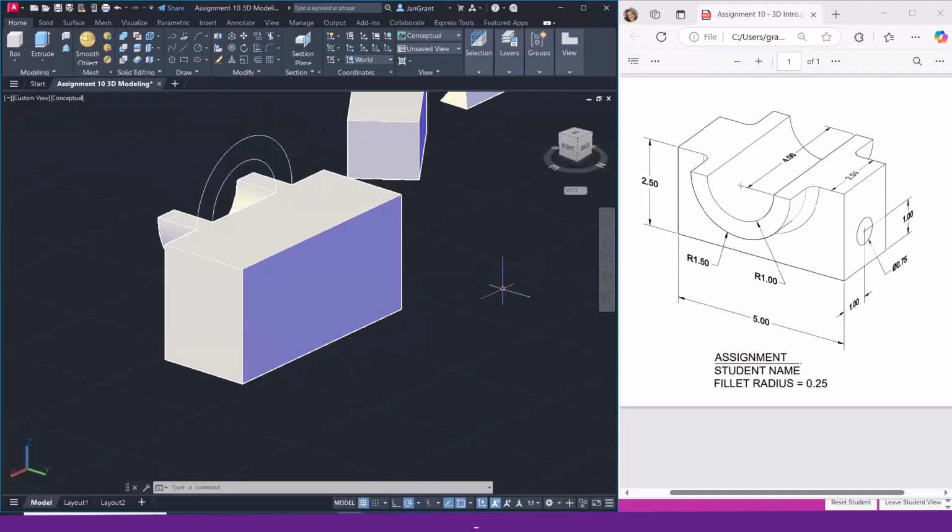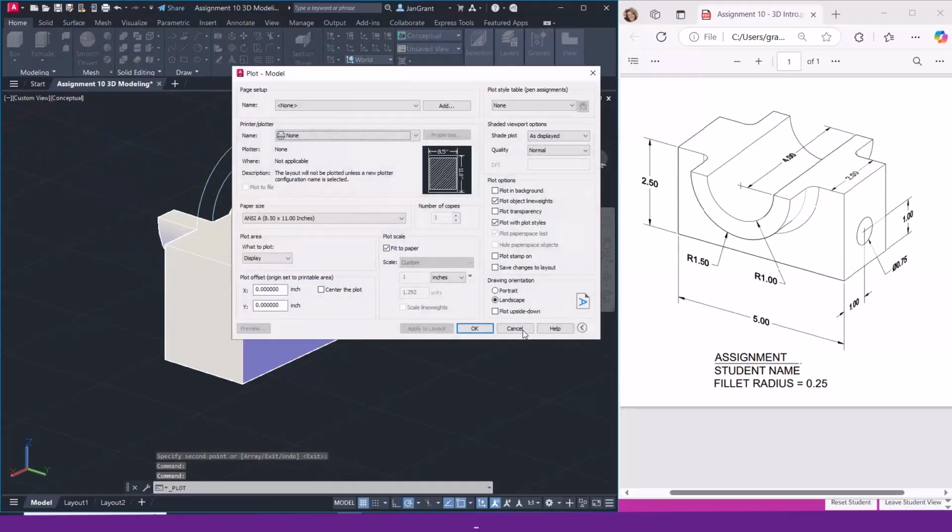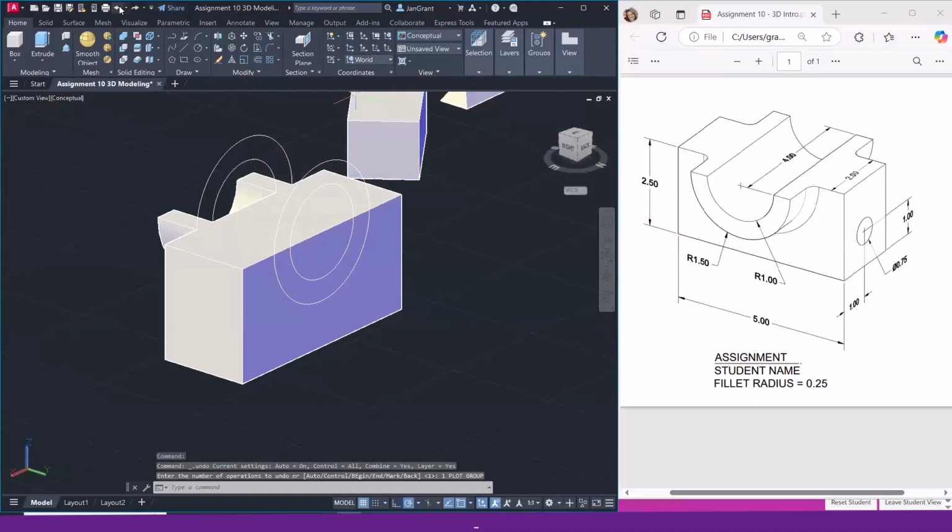I think because we're just starting out and we've already done the copy command a few times, let's make it easy, simple, and draw it. But just know that I could copy. I'll just show it to you. I'm going to start the copy command, select these 2 circles and enter. I can click this midpoint and this midpoint, and it copies it from one side to the other. So, oops, wrong one. So it's up to you.